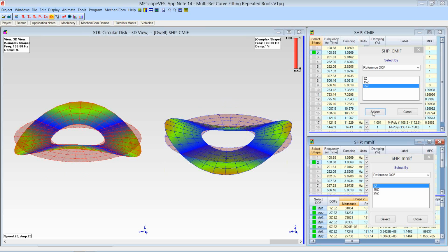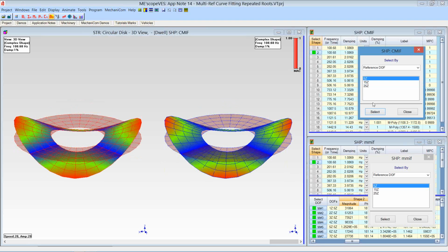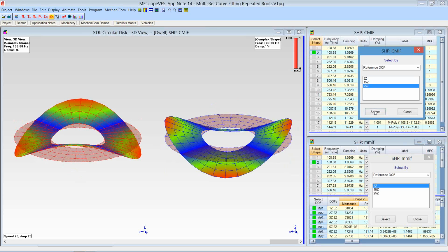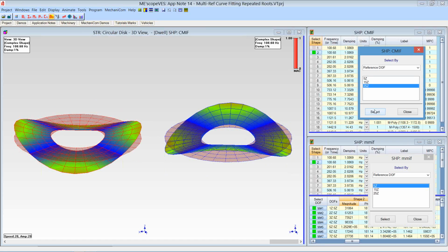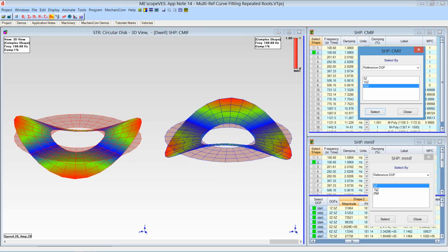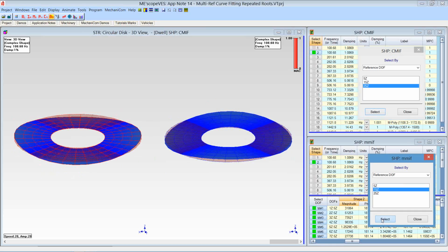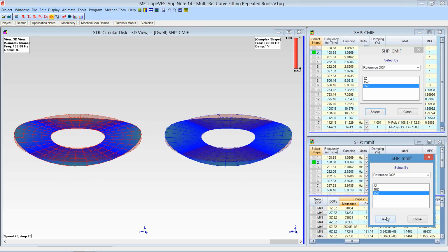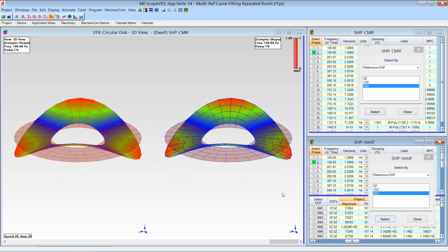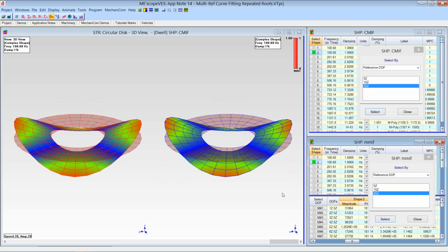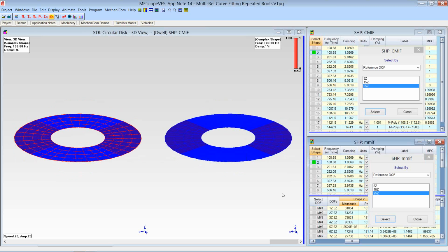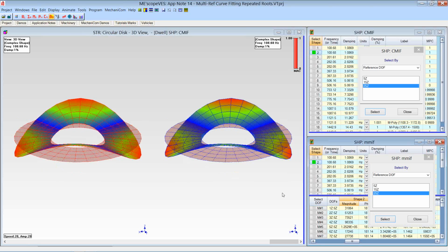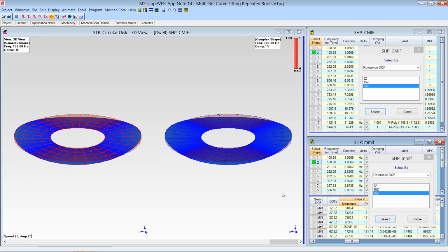So there is evidence of a mode shape. It doesn't matter which reference I animate from, I get the same mode shape. Same thing down here. I can switch down here and animate from a different reference, and I still have a MAC value of 1. I still have the same mode shape. And so what this is showing me is that the curve fitters, both these indicators, using their modal participation, the quick fit polynomial fitter went through and got the same mode shape from each of the references.